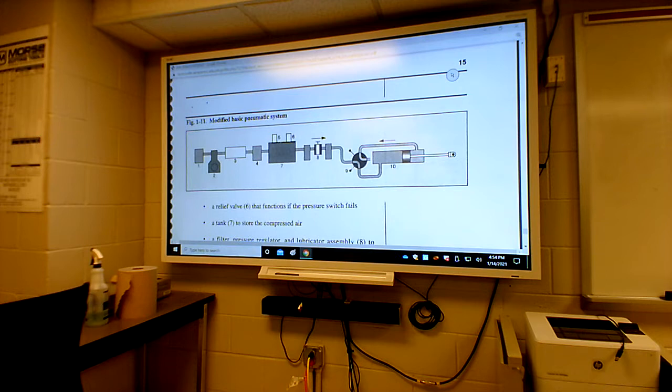As it runs, there's a little adjustment, a little screwdriver you can adjust. And if you have air flowing through it constantly, blowing through, you can set the drip rate. And there'll be ratings on machines, and they might tell you, you know, 1 drop per minute, 2 or whatever. And you'll set the drip rate whenever the machine's actually chugging and using air. If you overdo it, you'll saturate your lines, and then your discharge mufflers, they'll be pumping oil.